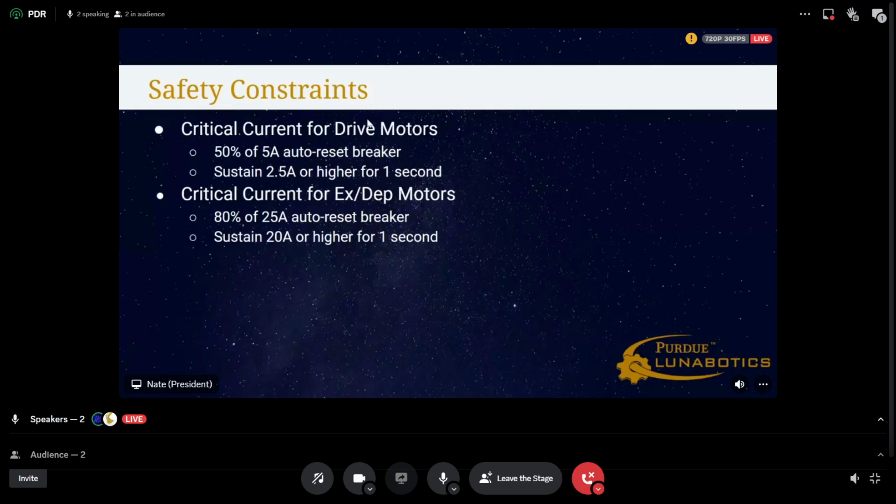So for how MPC closes the loop, the only input that rate-limits it is how fast we get an odometry update, which I mentioned was 10 hertz from our RTAB-Map. If we're already following a path, that's the only input to the control. We're also slowed down by the complexity of the MPC algorithm, so making it faster, like parallelization and a lot of other things we can add. So we wanted to clear that.